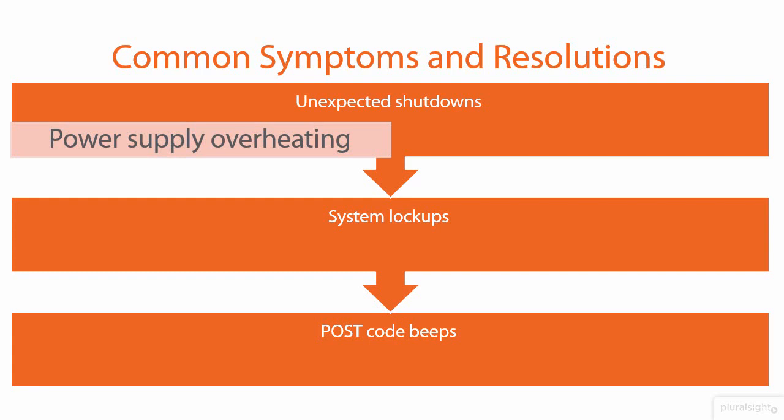Well, power supply overheating is going to be a common theme for many of these problems. Remember that the power supply is ultimately what powers the entire computer. And we have the ATX 24-pin connector and then individual component connectors that go elsewhere on the motherboard or maybe directly to devices like your video card and your hard drives and your optical drive. If the power supply is underpowered and you have too much hardware on the computer, then the power supply is going to shut off power as a fail-safe mechanism.